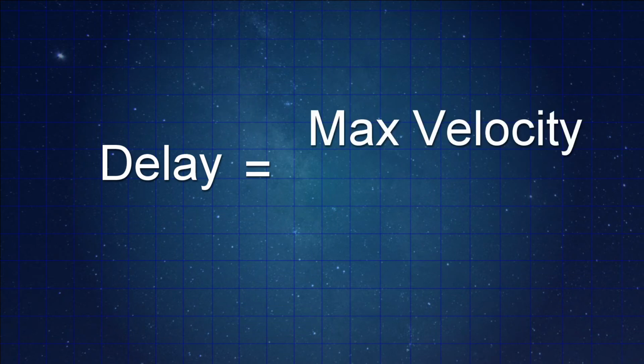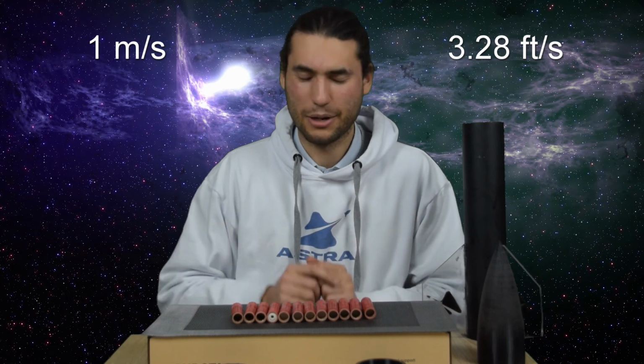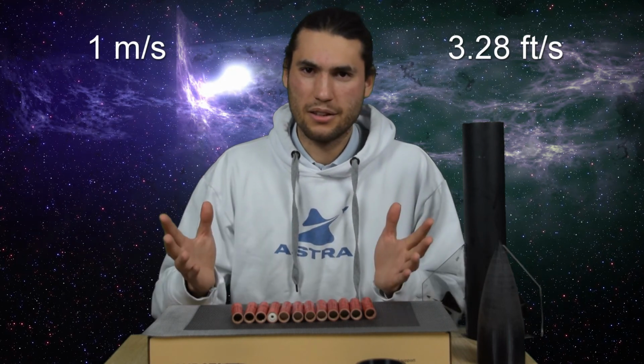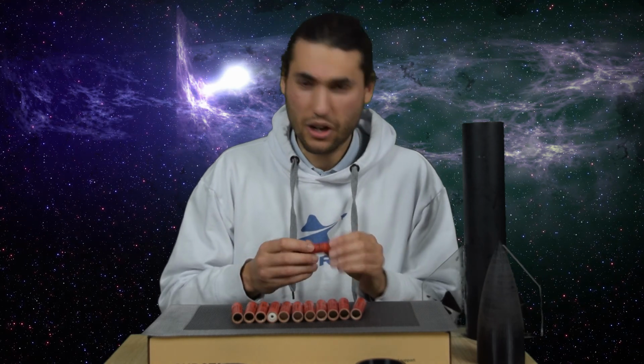To calculate the optimum delay time, you want to take the speed that your rocket will be going when it finishes burning the propellant and divide it by the gravitational acceleration of the Earth, which is 9.81 meters per second squared. Of course, you have to find the velocity of your vehicle in meters per second. You can find some conversions for that if you're working in feet per second in America. But yeah, if you find that duration, then that will be the optimum delay duration that you can have for deploying the parachute.